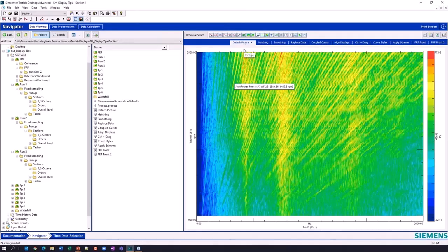So let's say I'm working on an engine or something and I've measured acoustic pressure versus RPM. So I've got this waterfall plot here, or a color map rather, and I'm looking at that frequency spectra versus that RPM sweep. I definitely see some interesting things along the orders, but I want to take a little bit closer look. I'm going to go up here to this little icon in the upper right, and it looks like a little plot with a little yellow starburst on it.